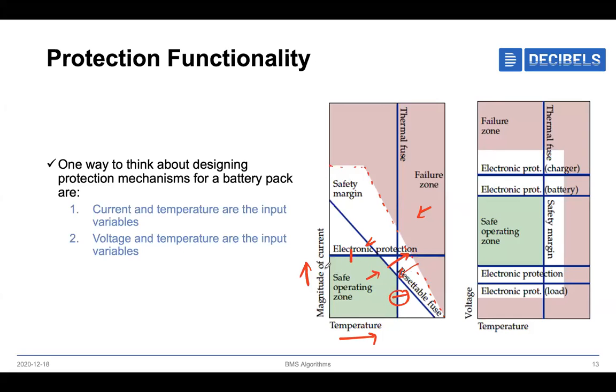We can give more protections also, like three degrees of protection and so on, but this is just an example I kept over here: one is temperature and the other is current. But the model which I'm going to show you will have three degrees of protection: current, voltage, and temperature. If any of these goes wrong, then the BMS will switch off the discharge and charge conditions.